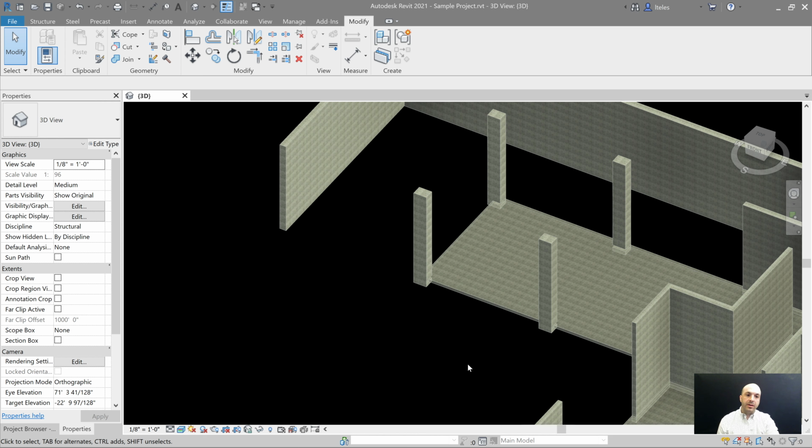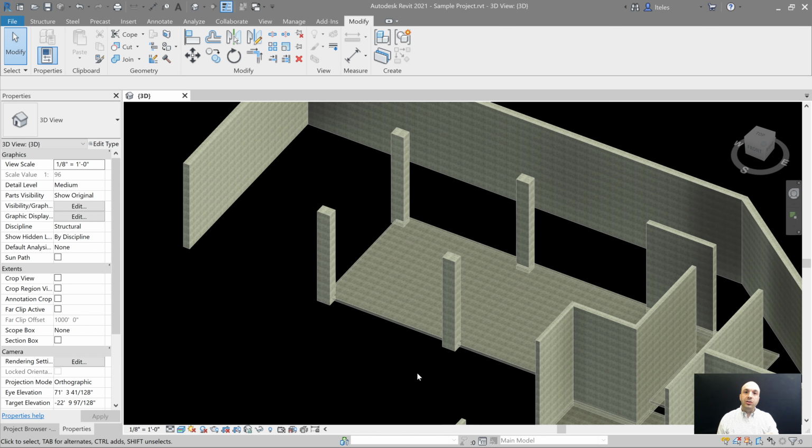We look at phasing there. The floor will wrap around those columns. But when we were modeling it and drawing the sketches of those floors, we didn't physically go around the columns. That's a lot of work when you're talking about a bigger project, going around each column, right? So all we did is we kept our sketch simple so that now we can do a Switch Join Order. So now let's go to our Modify tab, our Join dropdown, Switch Join Order.